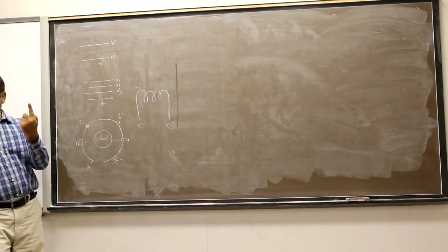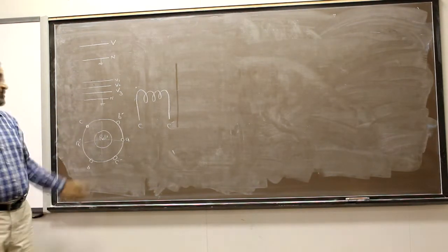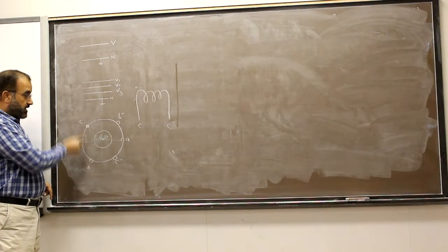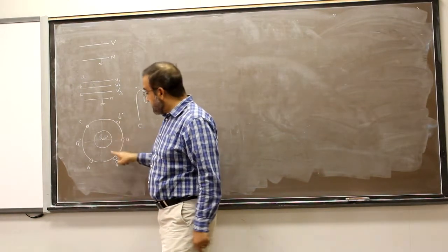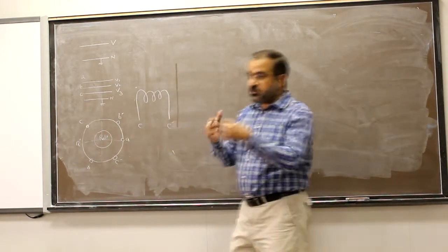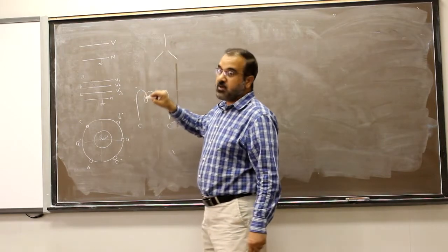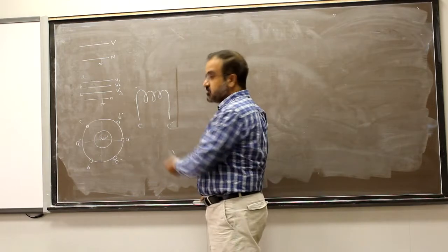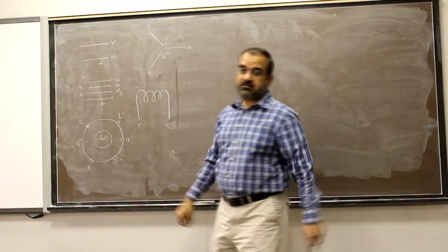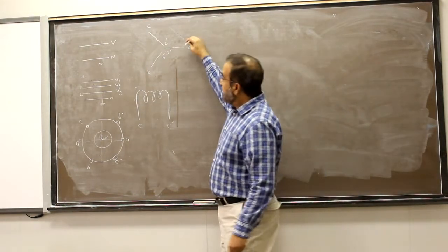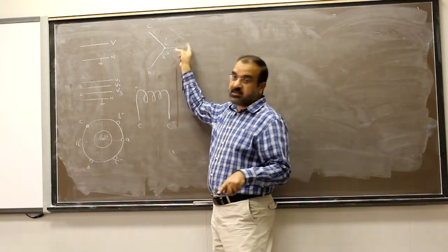Now A dash is one winding producing one voltage. B dash is producing another voltage, and C dash is producing a third voltage. Now if I take the voltages from this A, this B and this C, I will get these terminals. Then the fourth one, A dash, B dash and C dash, I will join them together to get the neutral point in case the generator is connected in Y connection. If I draw it similar to this one, this is A dash, this is B dash, and this is C dash, 120 degrees apart. Now if I join A dash, B dash and C dash together, this point is known as a neutral point in case of a Y connected generator.